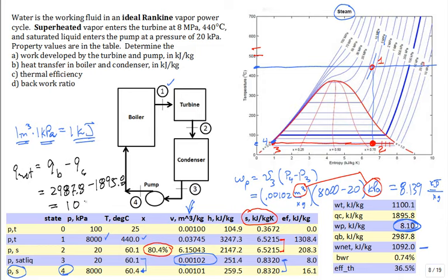1092. There you go. See, that's a good check. Yes, sir. What's your state 0 for? I often put a flow exergy column as a last column, and to do that, I need to know the temperature, enthalpy, and entropy at the dead state, knowing the dead state temperature and pressure of 25 and 100 kilopascal.